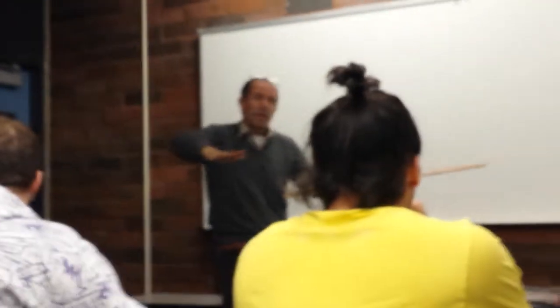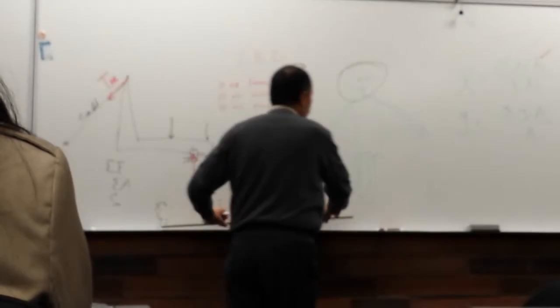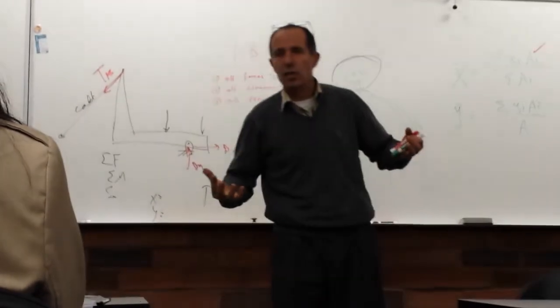Look, how wide is this? Correct? It is not one line. The weight on it like this. That's what we talk about, distributed forces, that we need to convert it into arrows, because we cannot deal with distributed forces when we make our calculations.